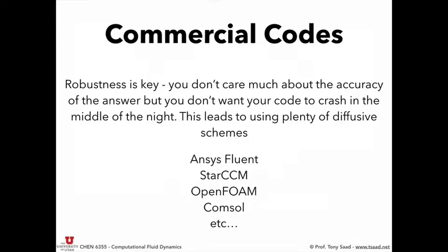You will learn in this class that 1 out of 2 times your numerical method is going to fail. And you're going to be like, oh, what is going on? And then you're going to have to analyze it and figure out that my time integrator was unstable combined with this spatial discretization, or my spatial discretization was dispersive, and things like that. And you have to go into the guts of it. Commercial codes can't do that.